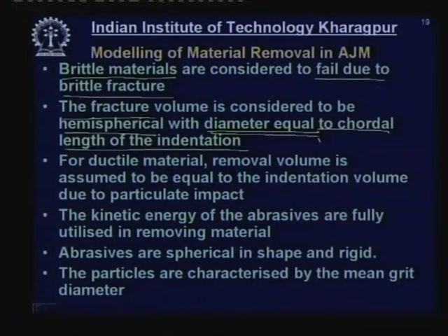That crater would be created because abrasive particles are highly kinetic energetic. So, the kinetic energy of the abrasive particle would be absorbed as it creates that crater, and the diameter of that particular crater or indentation would be equal to the chordal length. Another assumption is kinetic energy of the abrasive particles would be considered to be fully utilized.